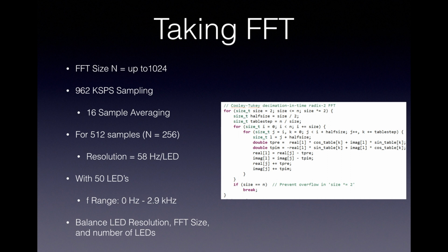Specific application requirements must be carefully considered when implementing this real-time audio device. Decreasing the frequency band for each LED requires increasing the size of the FFT. As this size becomes larger, the computation is too intense for real-time applications.